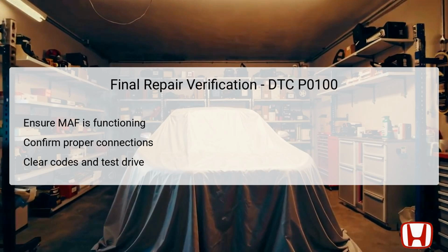After clearing the codes, a test drive should be conducted to monitor the vehicle's performance and check if the DTC reappears. This comprehensive verification process ensures that not only has the immediate issue been addressed, but that the vehicle is operating smoothly without further complications.